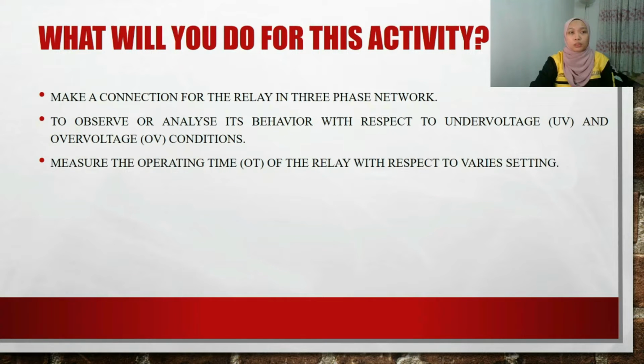Now I will explain what we will do for this activity. So first, we make a connection for the relay in three-phase network. Besides that, we observe and also analyze its behavior with respect to under voltage and over voltage condition. And lastly, we measure the operating time of the relay with respect to various settings.